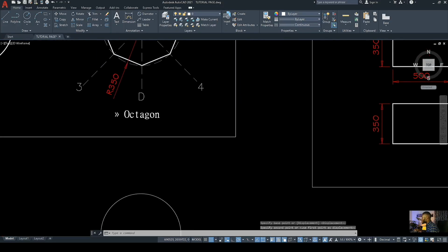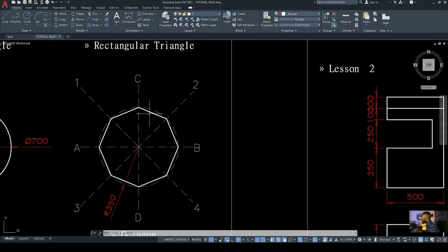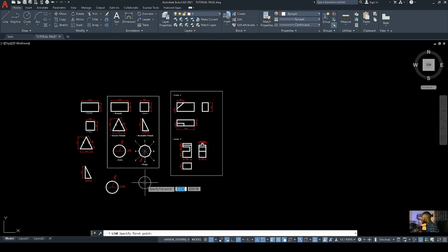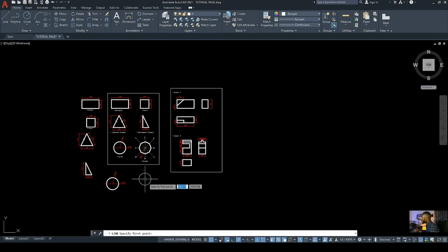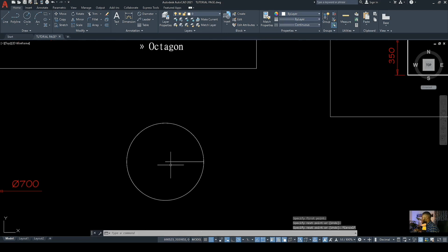So now, if you check on this, I used construction lines. I purposely left all of these lines to explain certain things to us. So now, to achieve all of these lines here, you just pick your line tool, then you come to your circle. You see, it automatically picks the center point since our snap tool is on. Then we click on it, then we drag to the circumference. After having done that, we pick this again, drag these points to the circumference.